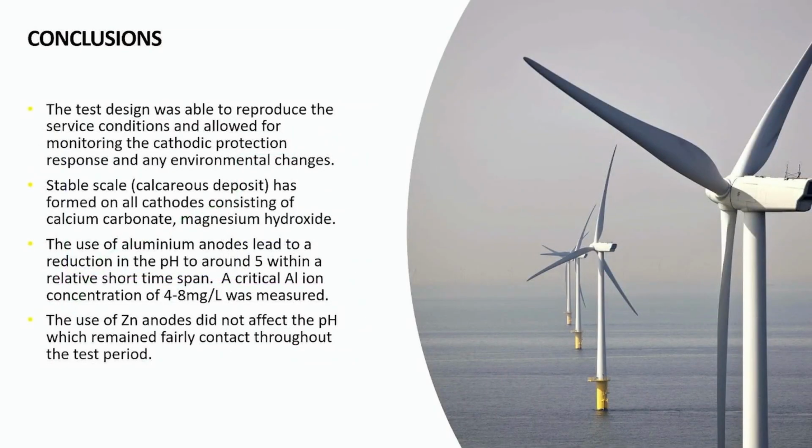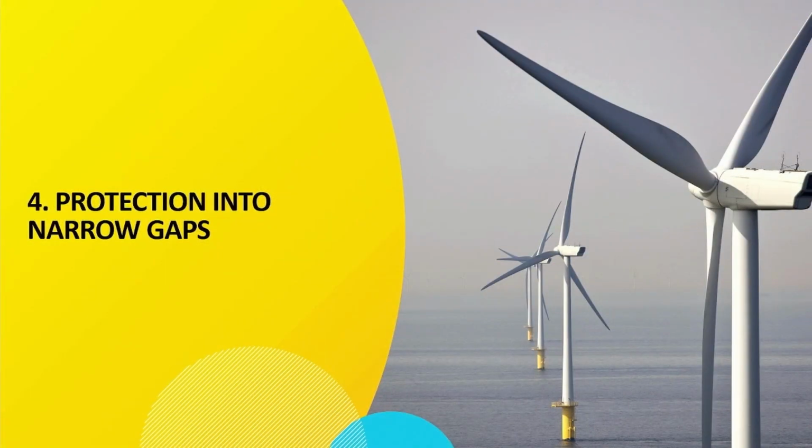So the test was successful. We got the stable calcareous deposit that we were expecting. We did see that the aluminium anodes created a reduced pH, but the zinc results were far better, and so zinc would be recommended for any other further retrofit applications.